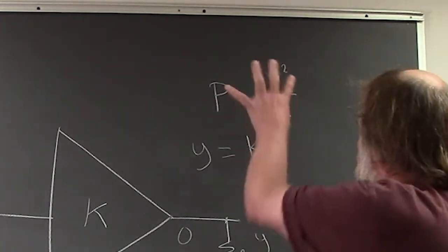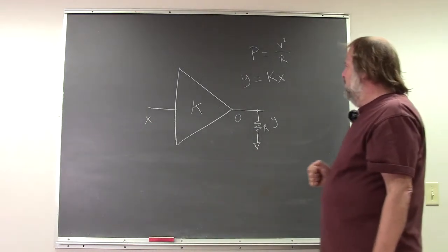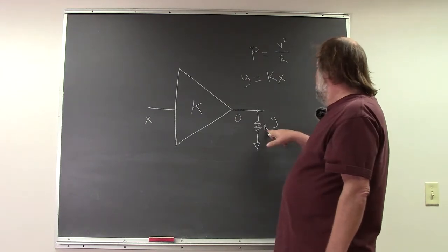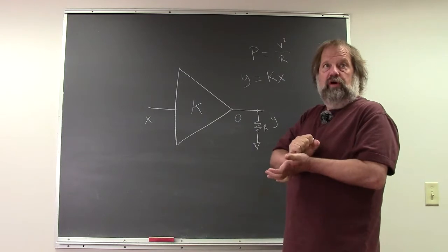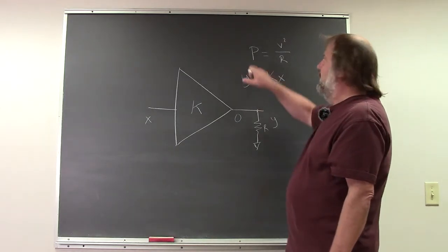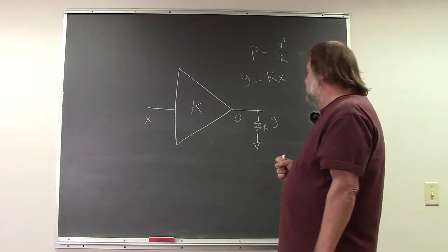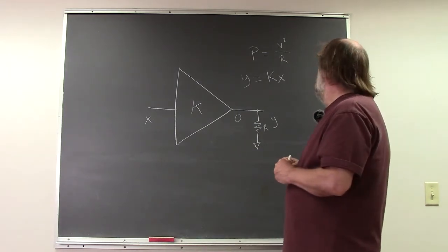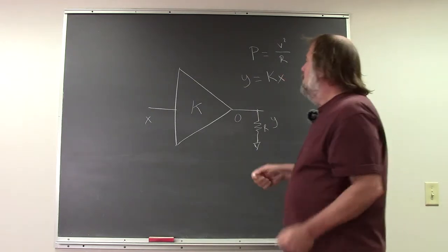What you can take from that in this ideal amplifier, because it has a 0 output impedance, is that as R gets small, in essence if R became a dead short, 0 ohms, this amplifier would have to source an infinite amount of power, which is not too likely to happen in anything you buy commercially. Nevertheless, it's a useful thing for us to talk about.